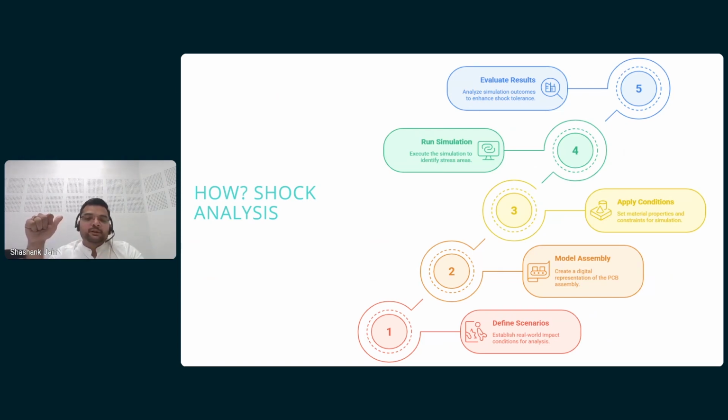This computational method is used in finite element analysis to simulate the dynamic behavior of structures and systems, particularly those with high speed impacts, short duration events, and large deformations which may occur in the system. Its applications include drop test, impact analysis, penetration analysis, crash simulations, and explosions. All these analyses can be done using explicit dynamics, which is a computational method in finite element analysis.